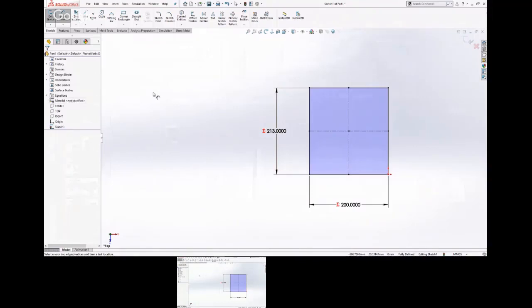The tool to use it is really cool. When you have multiple configurations, I think you right click and configure dimension. It's somewhere in there where you configure the dimensions and you'll see all the configurations and you can change it for each one. And then there's actually a rebuild light in there and you can click it and it'll go through and generate them all to make sure there's not going to be any errors. And if you put one of them way out of the range and it's going to cause the model to fail, it'll show you there's an error. So configure dimensions is the best way to do it.